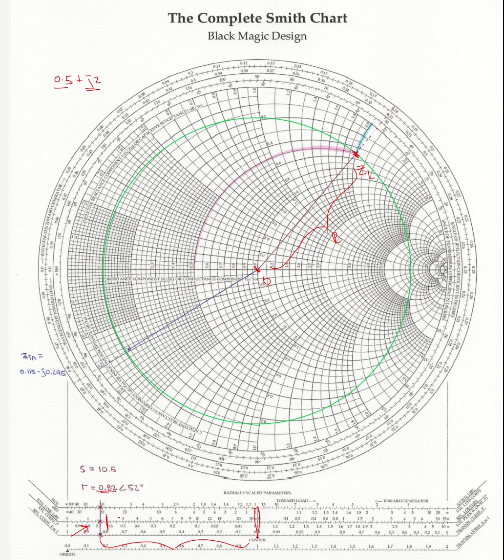In terms of the angle, all we need to do is follow this line all the way up, and we'll find that it's 50, 51, 52, somewhere in that region right here. And again, that's also reflected over here. In terms of finding the standing wave ratio, we can do that by simply following the arc of our circle down, and we'll notice this point right here.